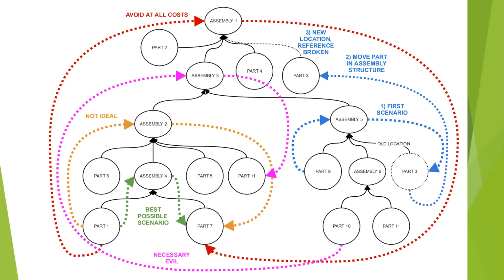There's an option in SOLIDWORKS that locks you to 1. If you have one reference here to here to here, and you try to make a second reference here to here to here, it'll just error out and say no. Now, the really screwy thing on SOLIDWORKS' side is if my setting says yes, and I create 2 references, and I send CAD to Robert, and Robert's setting is no, SOLIDWORKS is like, I'm told I can't do this, but it happened.